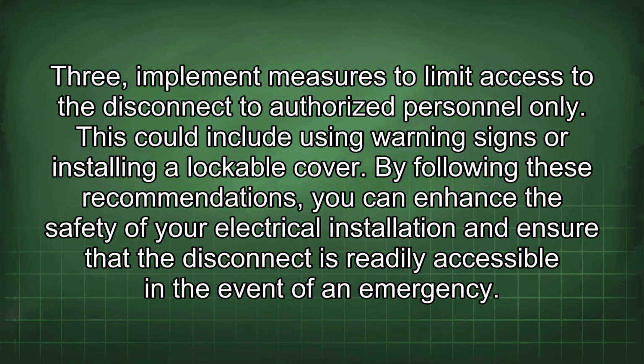3. Implement measures to limit access to the disconnect to authorized personnel only. This could include using warning signs or installing a lockable cover. By following these recommendations, you can enhance the safety of your electrical installation and ensure that the disconnect is readily accessible in the event of an emergency.